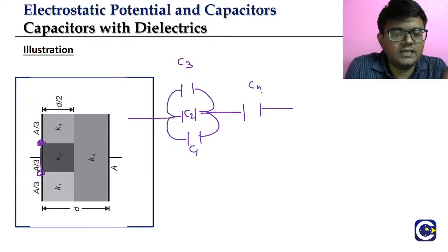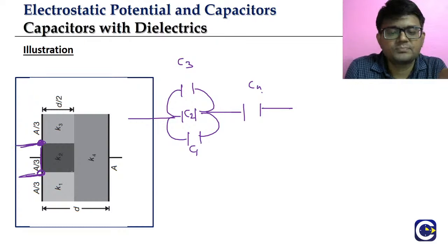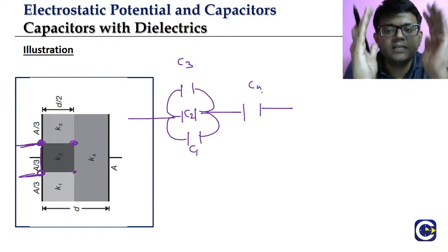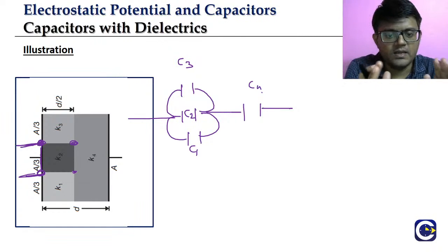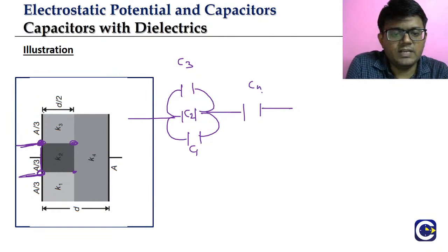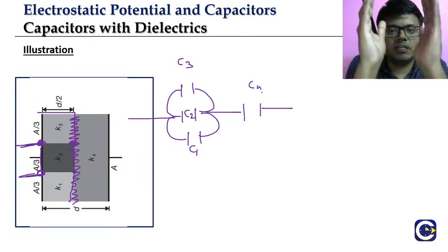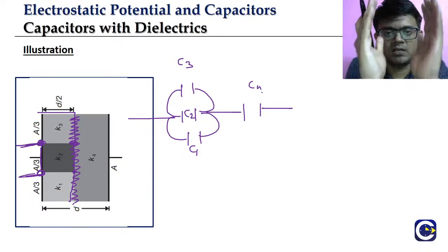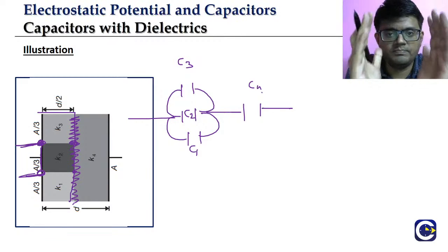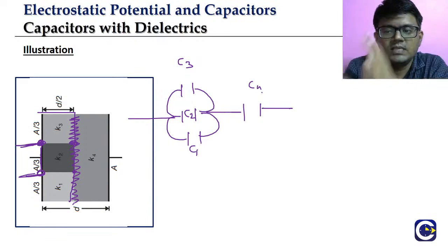Look here, place the terminals, and they are connected. Similarly here, terminals are connected. So C3, C2, C1, they are all parallel. Now look at the full block, this block is in series, because this is the common side. Which means that full block, C3, C2, C1, you can call it the parallel block, that is in series with C4.